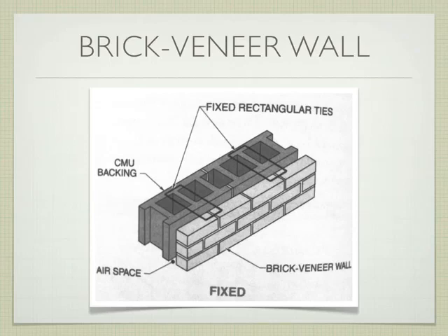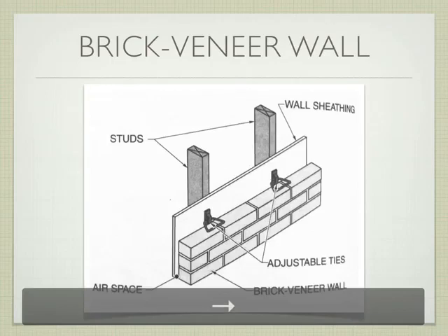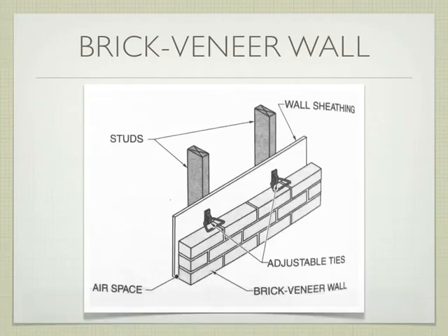Typically on a brick veneer building, if you look really carefully outside, you'll actually see some gaps in the mortar, or even some little tubes in the mortar, that allow this moisture to come out at the bottom. So once it works its way down, it can actually escape this cavity. Because if it didn't escape the cavity, that would be problematic. We'd get mold, no good. We'll talk about that in far more depth when we get to the exterior finishes lecture, which I think is maybe chapter 7 or something like that. I don't know. It's at the end.